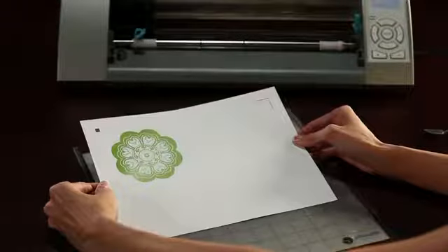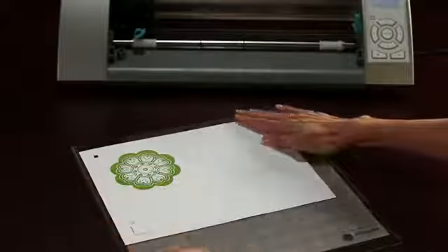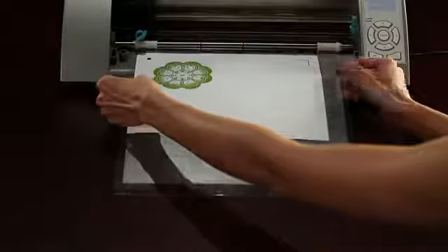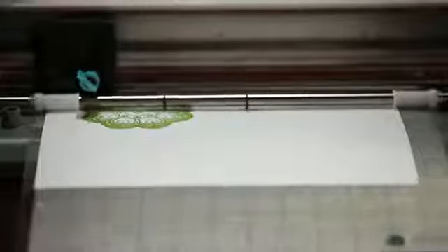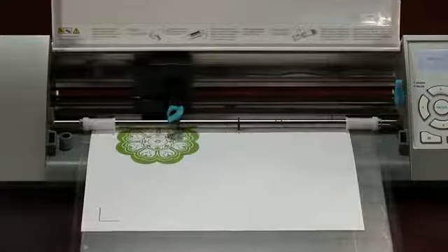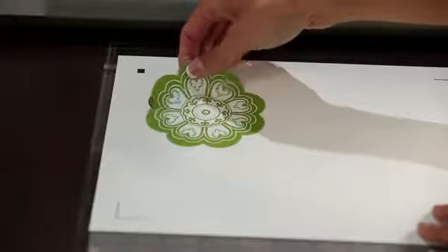Take your printed design and place it on the cutting mat in the upper left-hand corner as shown on the screen. Load the paper into your Cameo. Click the Send to Silhouette button and follow the instructions. Choose the link to automatically detect registration marks. The machine will use an optical sensor to locate 3 marks and align your printed image. Once the marks are registered, you can choose the appropriate cut settings and watch the machine cut right around the printed image.